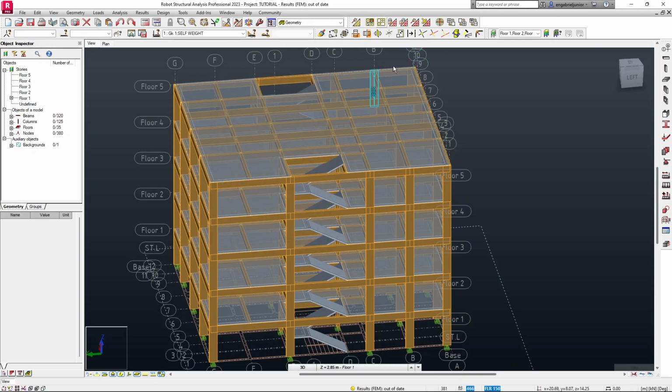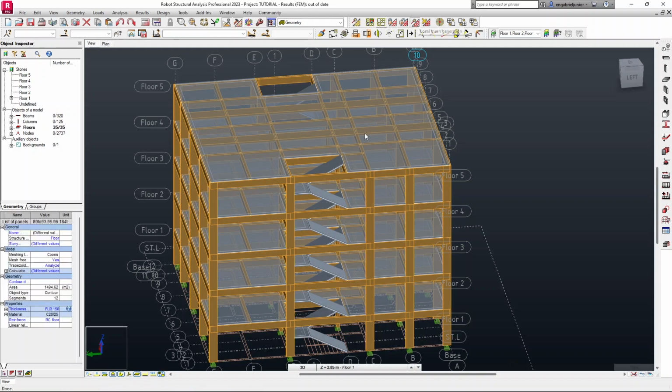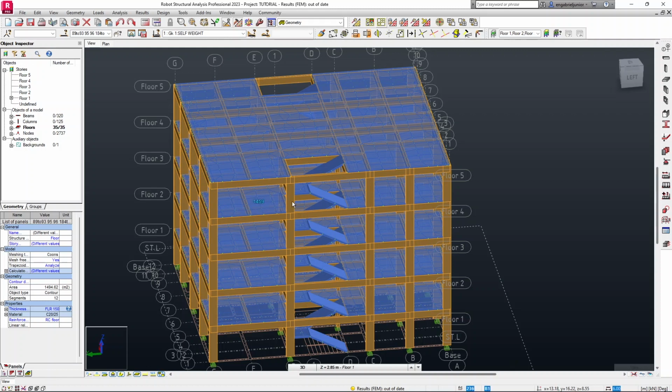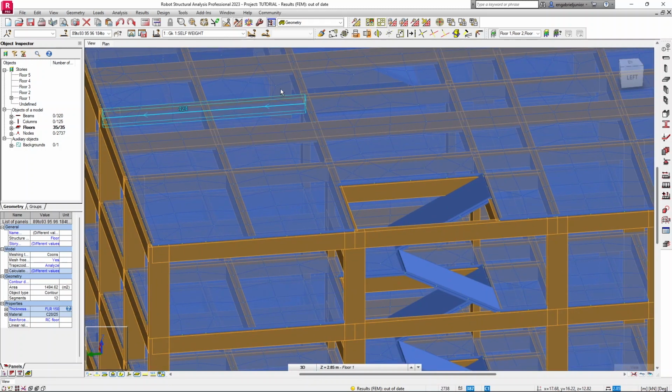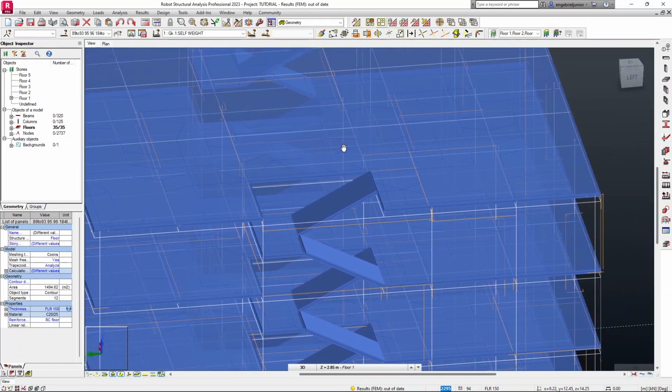So press on OK. Then go to these two options here. So the first one, we have local mesh deleting. Then we have local mesh generation. So for deletion, here is the case where we had created a mesh and we want to clear it up. Then for this one, we want to now generate a mesh. So click on it. Then immediately, if you look at the panels, they have some elements created on them. So we have some are rectangular, some are triangular, some of varying shapes.